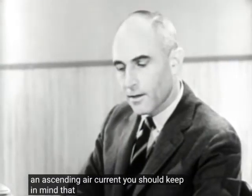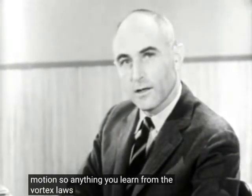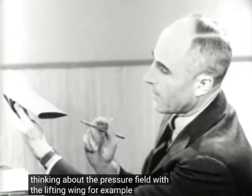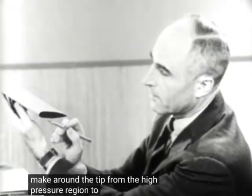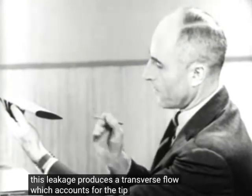You should keep in mind that the vortex laws come from the ordinary dynamical equations of motion. So anything you learn from the vortex laws can also be found by thinking about the pressure field. With the lifting wing, for example, air can leak around the tip from the high pressure region to the low pressure region. This leakage produces a transverse flow which accounts for the tip vortex.